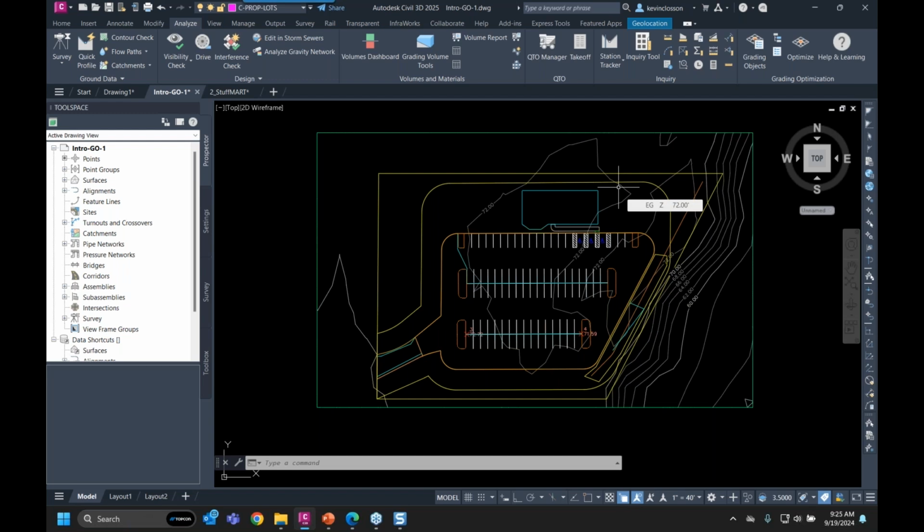So these are required elements going into utilizing this optimization tool. You have to have an existing ground surface. That's the number one thing right off the bat. If you don't have that, you know, because it's comparing that surface, obviously, for volumes. I mean, that's the easy part. But it's also trying to figure out how can I cut this down or fill in specific areas to make sure that we end up having the entire site mathematically work. So that is one of the key pieces.